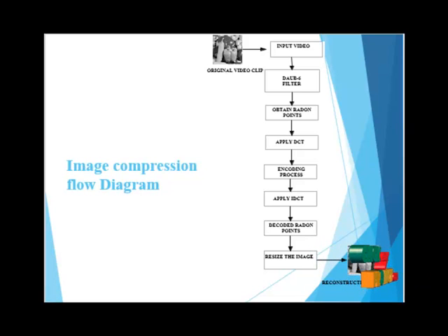This is the pre-process we considered. Then the image is split into 8x8 blocks of pixels, and then we apply the DCT. This is a DSP image processing algorithm for applying the DCT, and then the encoding process. This is the compression process, where we encode some values.